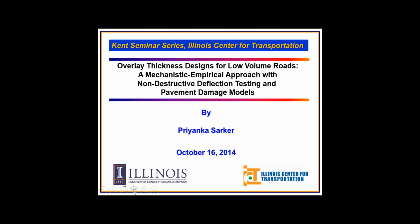For 2 years, we've been running the FWD polymer deflectometer device. Basically, we had to reassemble it with the help of research engineers here, and go out to local roads and streets doing FWD testing to assess the structural condition. All for the effort of coming up, in this project, with overlay thickness designs for low volume roads based on non-destructive testing and evaluation of existing pavements. She's going to talk about the project progress and findings. We're coming close to actually finishing the project now.